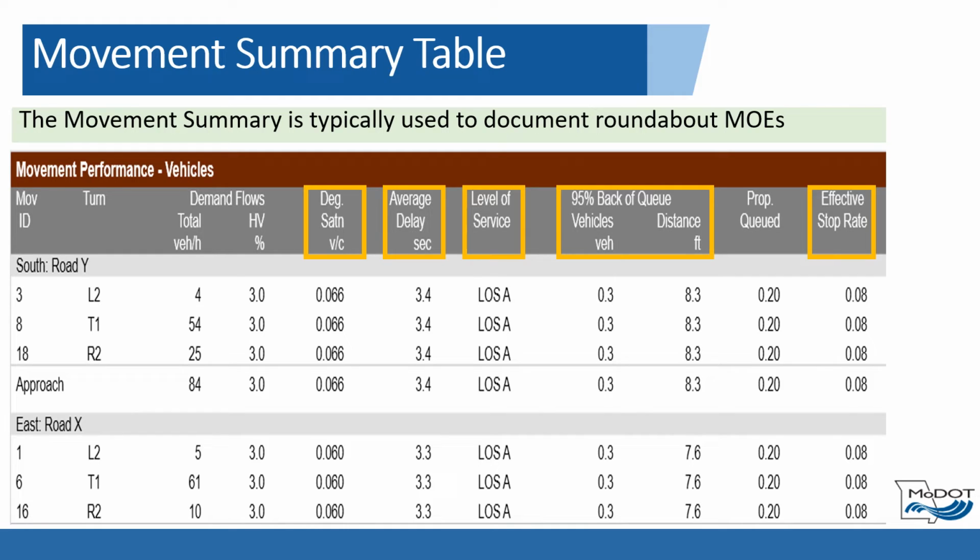The user should take a comprehensive approach to roundabout analysis and be sure to assess all primary MOEs as part of the big picture of roundabout operations. For instance, if a LOS is reported as a D or better while volume capacity or queue lengths reflect poor operations, then the intersection or lane group could be considered as having the equivalent of a failing LOS.